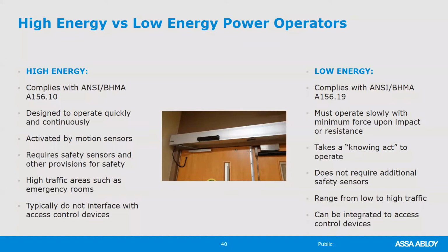In fact, many of Norton's power operators that are used in hospitals have onboard built-in power supplies that can power your accessories, like either an electric strike or a maglock or an electric latch retraction exit device, provided that it doesn't have the large inrush. It has to be a motor-driven one, like the Sargent 56 or the Corbin Russell MELR, the motor-driven electric latch retraction, less than an amp to power.